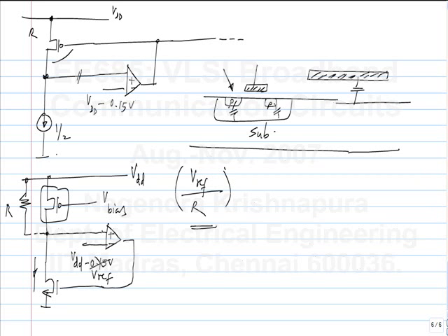So in this particular case, the current is inversely proportional to the resistance. So if you pass this current through any other resistance of the same type, let's say this is N-type polysilicon, and you take any other N-type polysilicon resistor, not necessarily of the same value. Usually it's the material properties that change, right? It's the rho that changes, and also the temperature is common to the whole chip. That's the assumption.